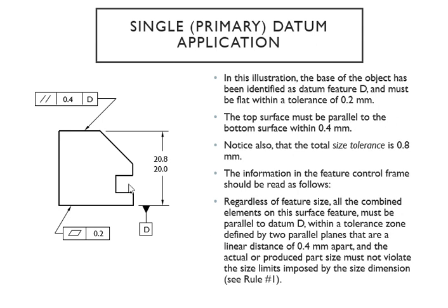You have three things going on. Your control frames right here, okay? Datum reference. You have parallelism between the surface and that, and it's got to be within 0.4. We're in millimeter system because you have a 0 written in front of your decimal. So just by looking at the values, you know that you're in millimeters. You have to learn how to read your drawing or someone else's drawing, okay? Single primary datum is right here.